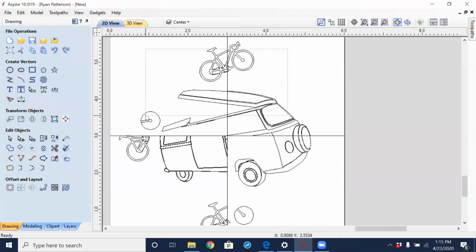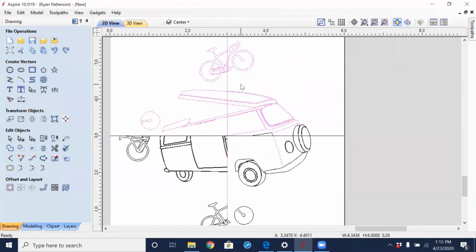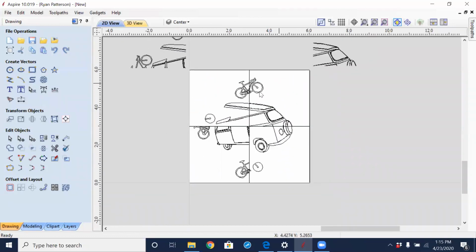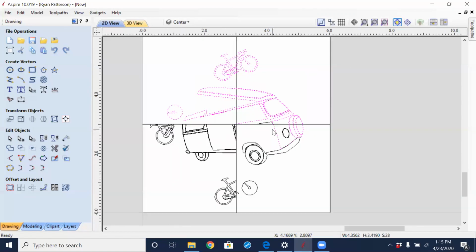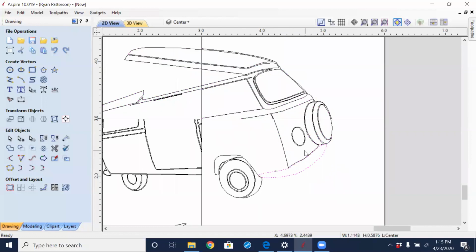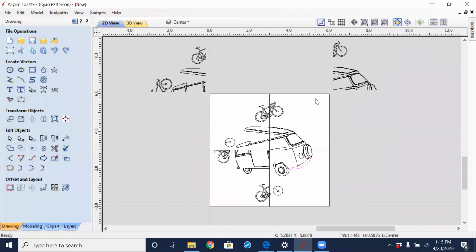There it is. So again, going in and selecting all of that. Now, one thing I just did right there was a sweep select, going from left to right, because I want to make sure that I get all of the objects that are inside that bounding box. But in doing so, I happened to select an object that I did not want to remove, which is this line. So holding the shift key down and doing a little selection of that, I'm going to remove that selection from my main. Oh, there I did. So let's try that one more time.